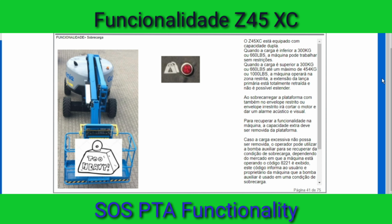Overloading the platform, in either the restricted envelope or unrestricted envelope, will cut the engine and give an acoustic and visual alarm. To regain functionality in the machine, the extra capacity has to be removed from the platform. The operator is allowed to use the auxiliary pump when the platform is overloaded. However, this action in specific markets is recorded and indicated on the display with the code 8221.